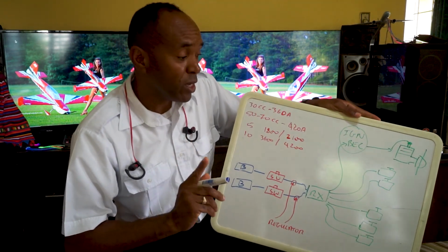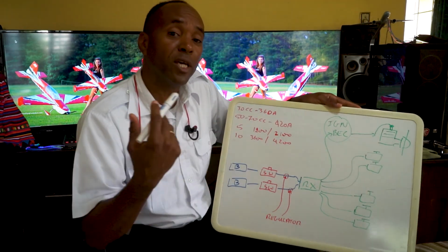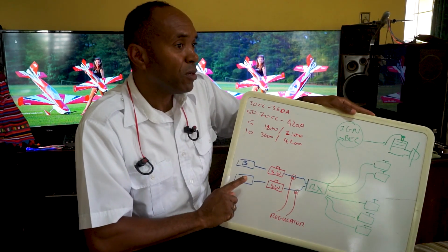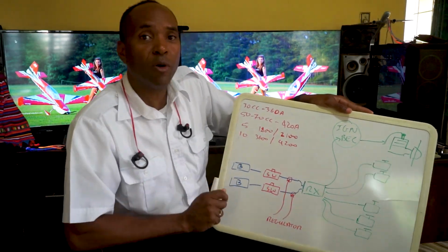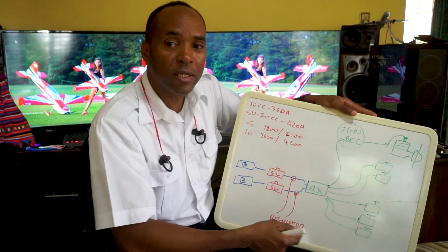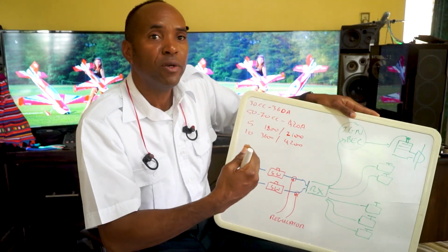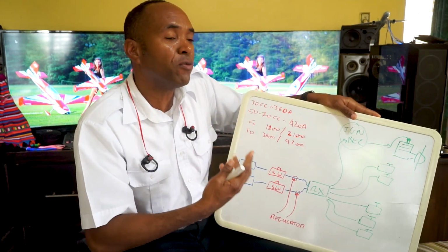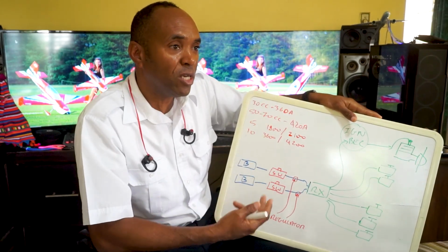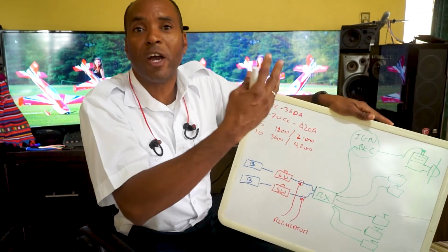Now what you have to do is to find out what are the limitations in this system, what is the weakest link here, because that is going to impact the safety of your setup. Right? You need to find out what is the voltage tolerance of each component there, and what is the maximum amperage that each component requires or each component can manage, right? And you are going to make sure each component exceeds the requirement, in terms of your current producing capacity and your maximum voltage, by at least 25%.